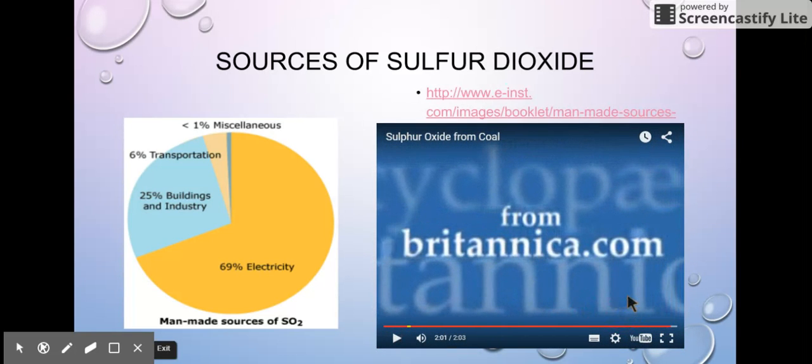Okay, so the important point there is, in order to reduce the effect of the production of sulfur dioxide, we can actually react it as it comes out of the smokestack, and that means we can neutralize it, because remember, an acidic oxide plus a base is still going to make salt and water. And the base that they're using is called lime, which is actually calcium oxide or calcium hydroxide. So they're using something which is readily available, and it removes the sulfur from the smokestack, and it produces the solid that you found being piled up in that image.